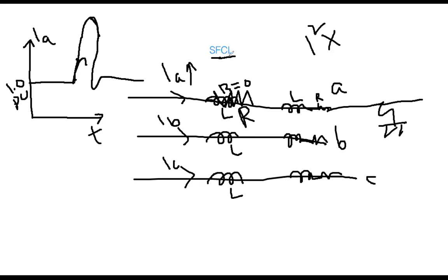That's why it is called a fault current limiter. Once current increases beyond a certain value, whatever technique you use to cool it down, it cannot. Its resistance increases, and it appears as a very high value of resistance, and that impedes the fault current.